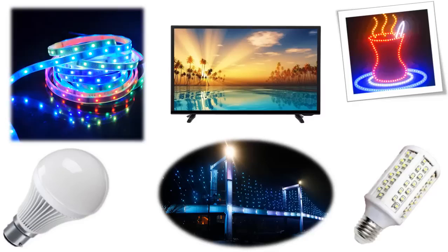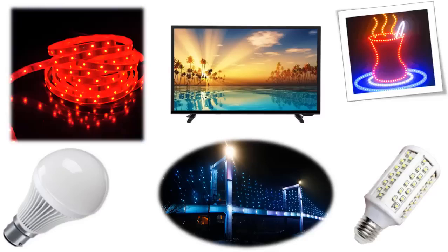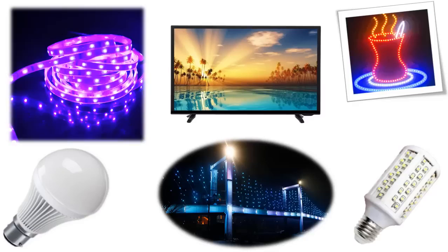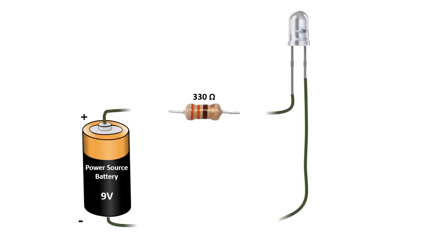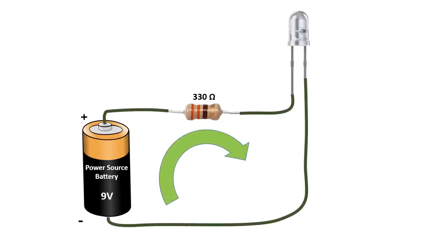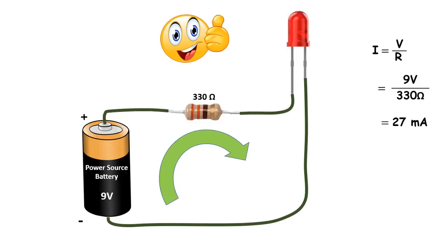The first indicator that the LED will have is a longer positive lead, the anode, and a shorter ground lead, the cathode. The other indicator is a flat notch on the side of the LED to indicate the positive anode lead. Like all diodes, LEDs create a voltage drop in the circuit, but typically do not add much resistance. In order to prevent the circuit from shorting, you need to add a resistor in series.